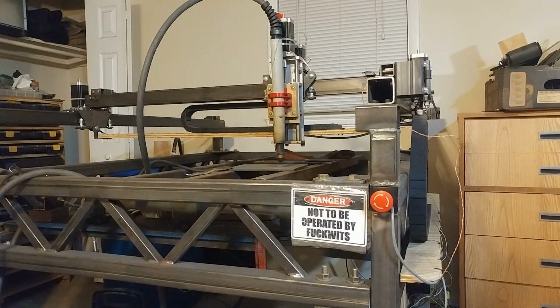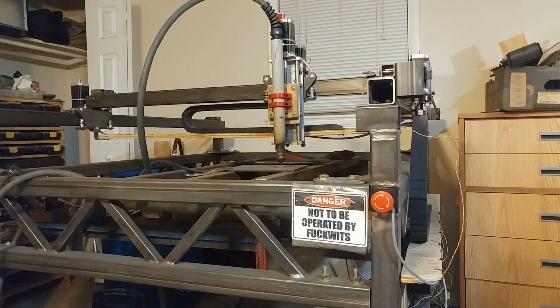And that will let us keep that torch at the right height, even while we're in the middle of a program. Of course, this does mean watching the plasma torch as it cuts. So you're both babysitting the machine, and you do need to wear a welding mask because it's a plasma arc and otherwise you'll go blind. But for a very simple solution you can do in a few lines of HAL, it does work pretty well.